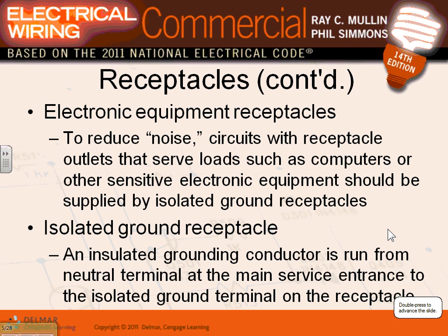All right, if you have electronic equipment like what we did in our project, there's a lot of interference with electronic equipment, so the engineers decided to have an isolated equipment grounding conductor. You can see if you look at our spec here, it calls for an isolated ground receptacle, isolated ground conductor to be installed with every branch circuit to feed these receptacles.